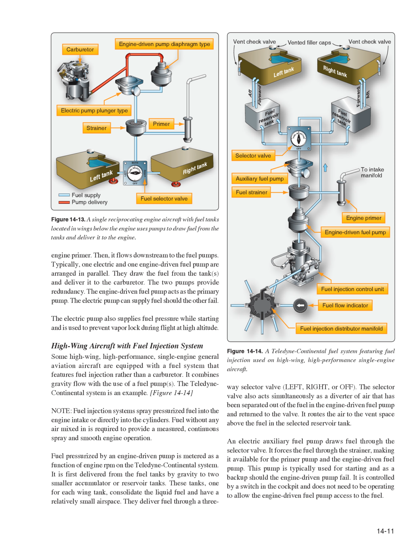The selector valve also acts simultaneously as a diverter of air that has been separated out of the fuel in the engine-driven fuel pump and returned to the valve. It routes the air to the vent space above the fuel in the selected reservoir tank.